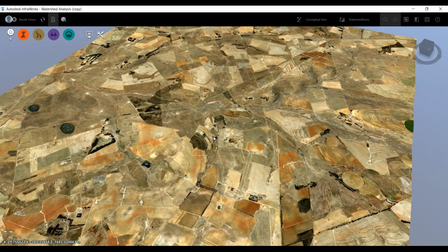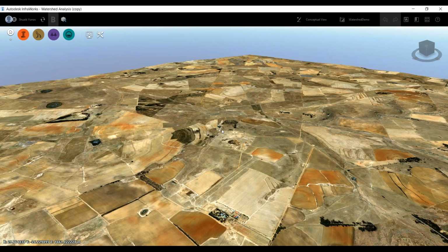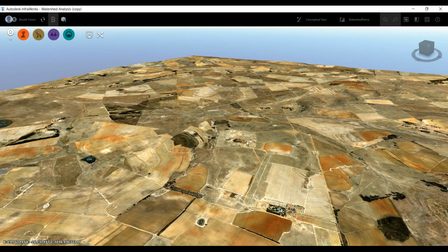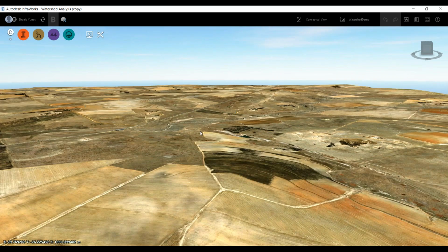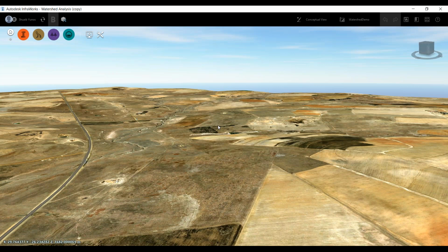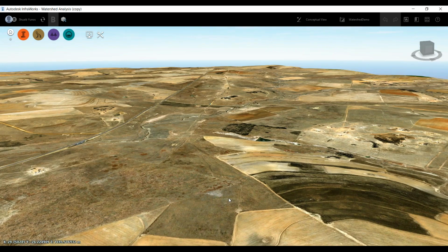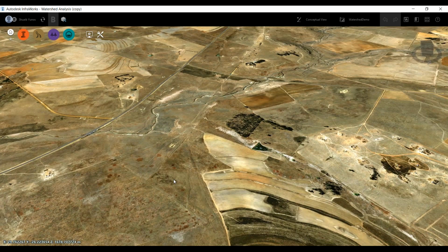Okay, and the reason being is if you look at the topography, it's not really defined. So normally I've looked at watershed analysis done by some of my colleagues, and it's normally for ridges or valleys that are very easy to define. So if you look at it on maybe Google Earth or something like that, you yourself can define the extent of the catchment, right? But what if the topography is very mild or medium in nature, like what you're seeing right now? It's very hard to check the slope, where it's more or less a concave, where the water is going to be draining to. It's very hard, right? So you can see here, I've taken a challenging model for the same reason. So I hope you appreciate that.